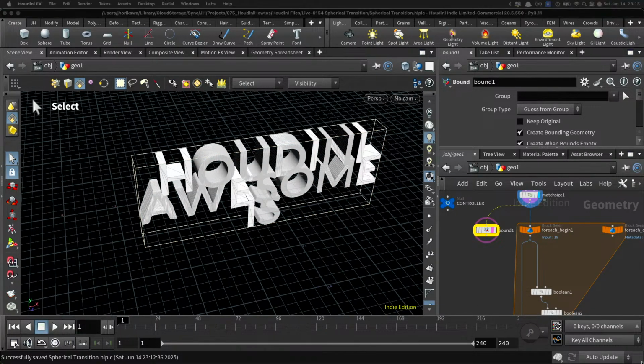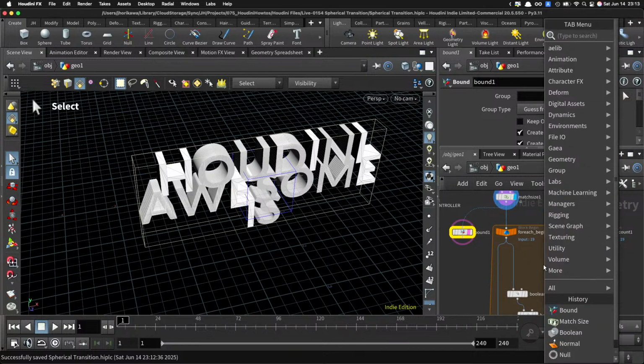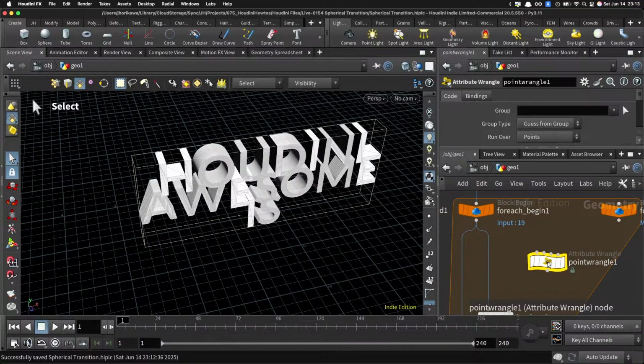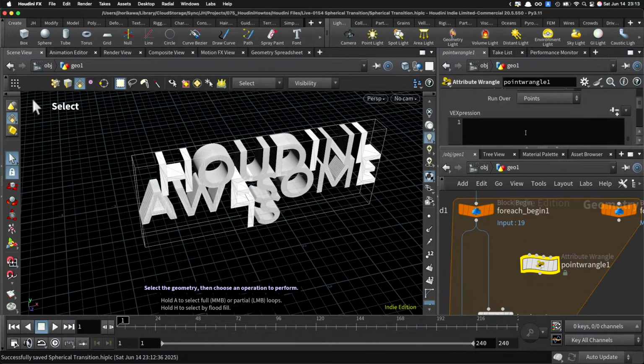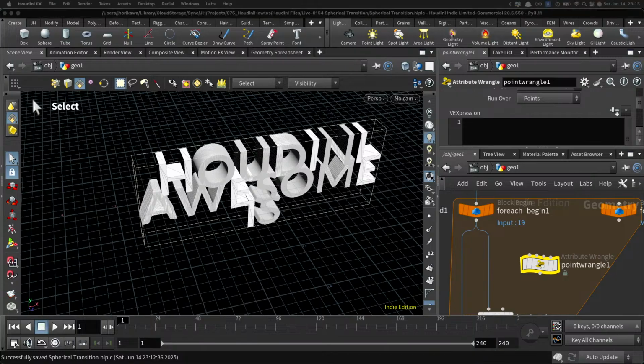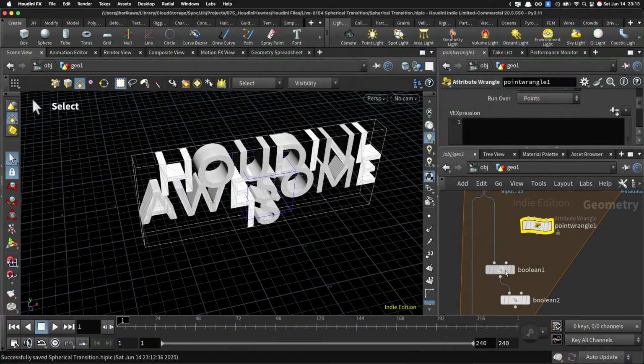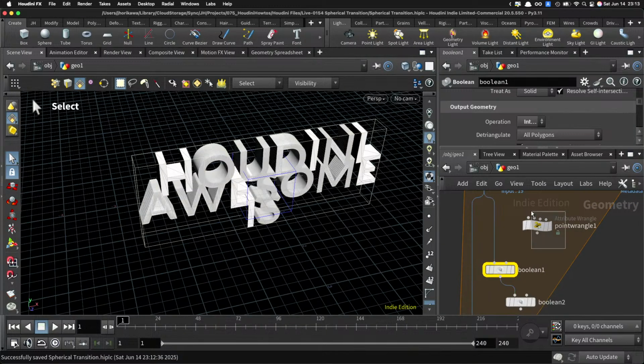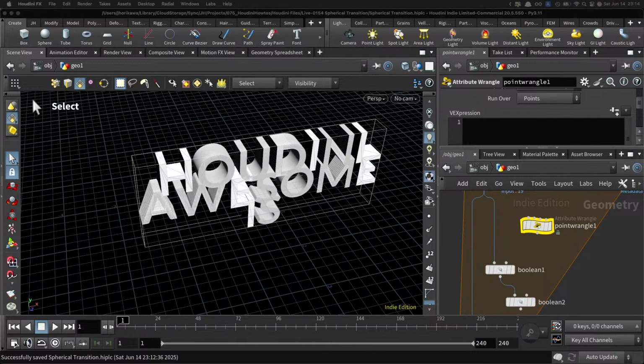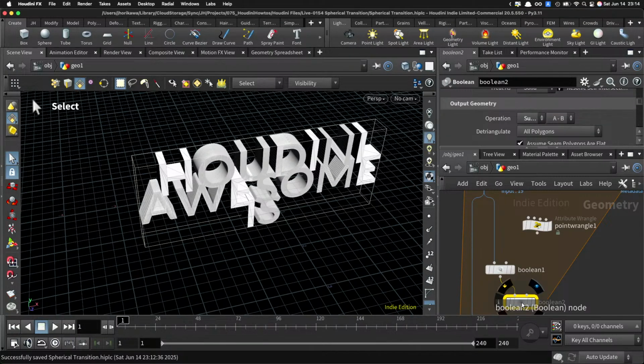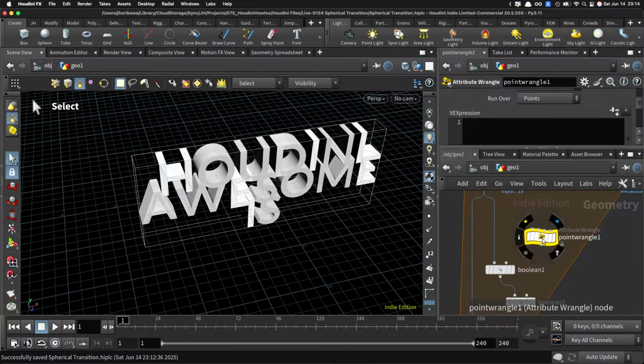So to do that, first of all, I am going to create 2 points, I guess, because we need one for the intersection and one for the subtraction, and each of those sizes is a bit different. The size for the Boolean subtraction will be a bit smaller.